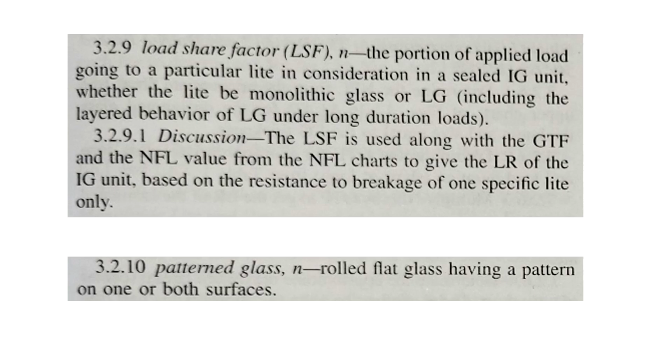Okay, discussion. The load share factor is used along with the glass type factor and the NFL, the non-factored load value from the NFL charts, to give the load resistance of the insulated glass unit based on the resistance to breakage of one specific light only. So if you've got laminated glass, that's not for both of them to break, that's for one of them to break. That's going to be the load resistance of one light, the load resistance that would cause one light to break only.